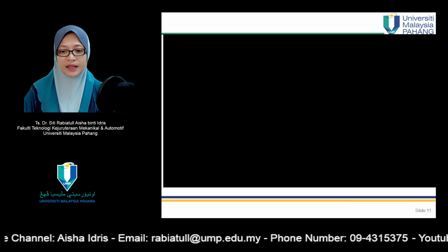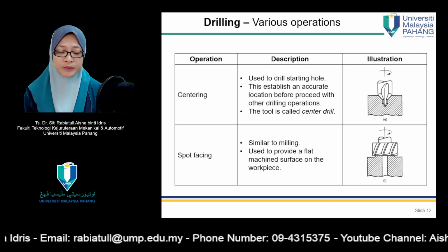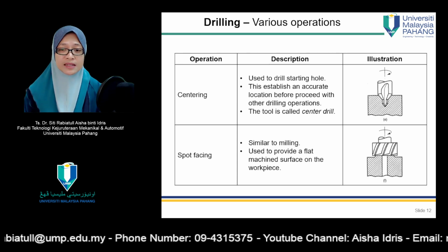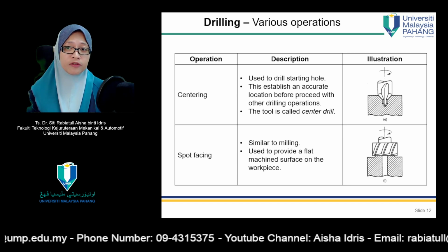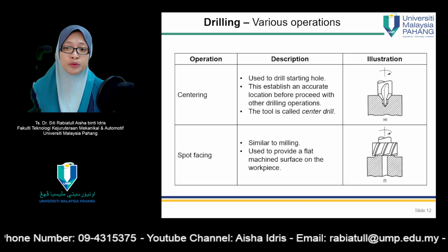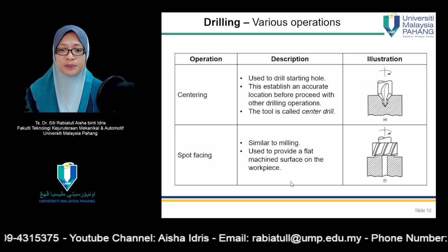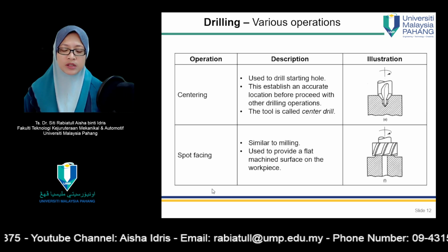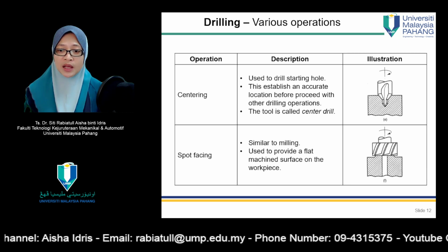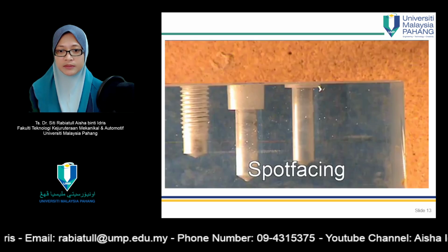Okay, so that is it. And other than the previous various operations, there are other types of operations as well, like centering, which is normally used for creating a hole before starting drilling. So that is centering. And then spot facing. Spot facing is more or less the same as milling. It is used to provide a flat machined surface on the workpiece.